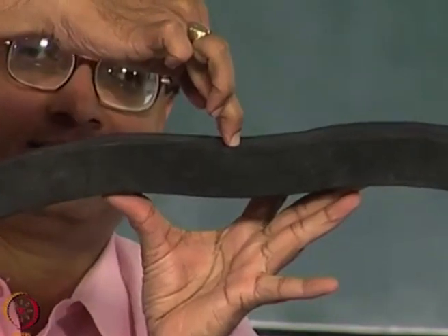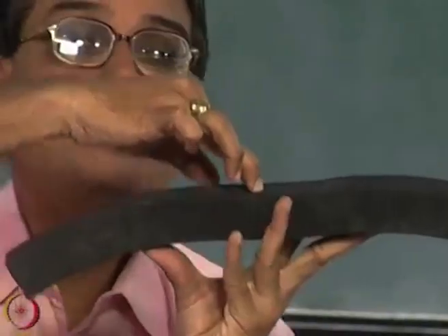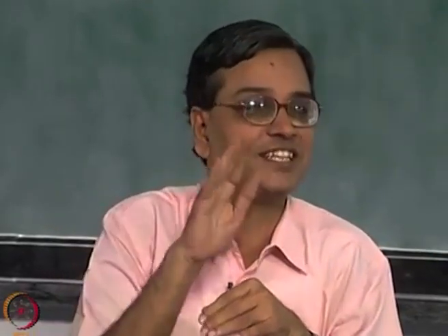It is a parabola. But what will be the variation when I come closer to the loading point? It is no longer a parabola. In fact, if you look at the way you learnt shear force and bending moment diagrams, you started with concentrated loads. But in theory of elasticity, you would have started with distributed loading, because with distributed loading I can specify the boundary condition easily. I will find it extremely difficult to specify the boundary condition when I have a concentrated load.